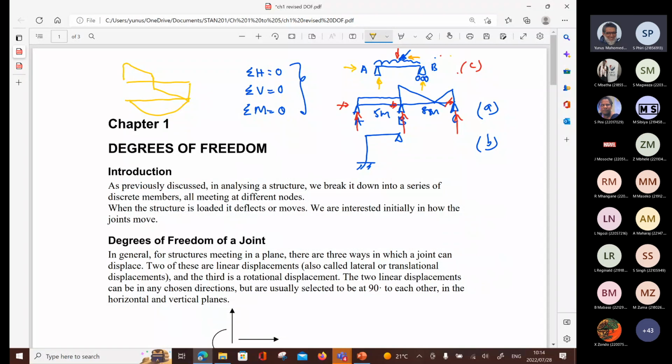So we're taking the difference between the loads and the reactions. Unfortunately, this doesn't give us an answer. I've got three unknowns and I know the loads, so I'm sitting with three unknown values summing up to a load. If I take moments about A, I have B and C as unknowns. If I take moments about B, I've got A and C as unknowns. If I take moments at C, I've got A and B as unknowns. I could generate all these equations, but where would I go with it?